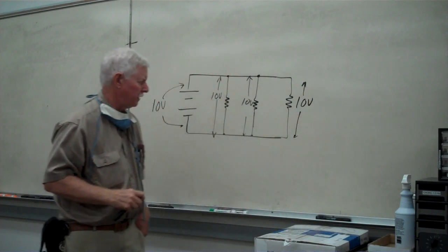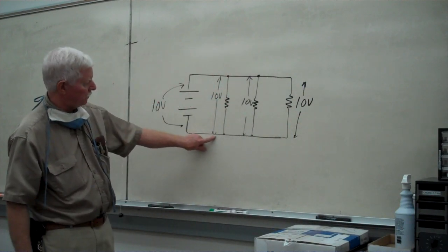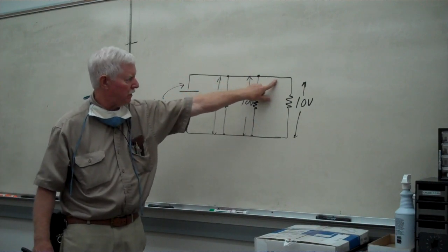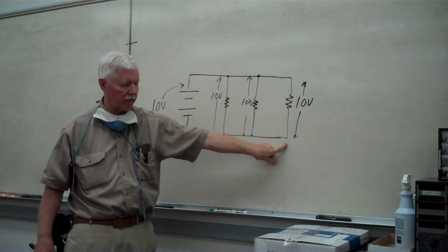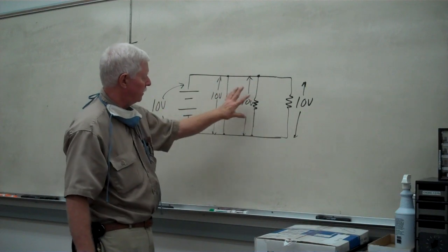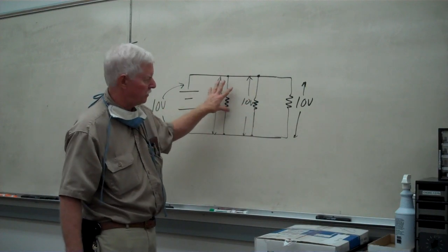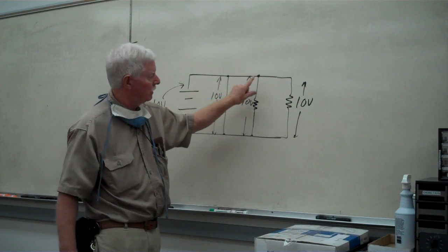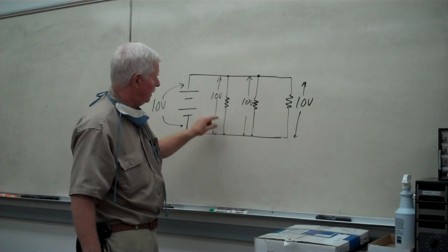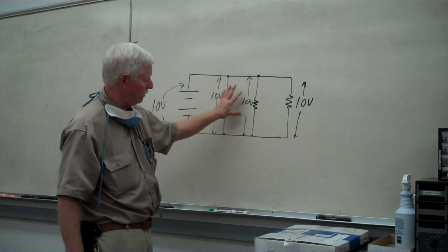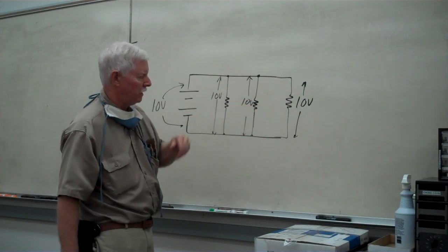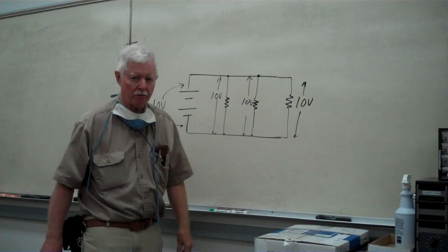That way, for the purpose of the analysis between troubleshooting and designing a circuit, this is assumed to have a lot less loss than what might be assumed if each one of these conductor lines were, say, hundreds of feet long. So, as we're looking at the circuit, if we put 10 volts across this line, because the wires actually are going to be connecting to all of these at the same types of points, this will have 10 volts across this load, 10 volts across this load, and 10 volts out across here. If we change it, it'll be the same out across each one of those.